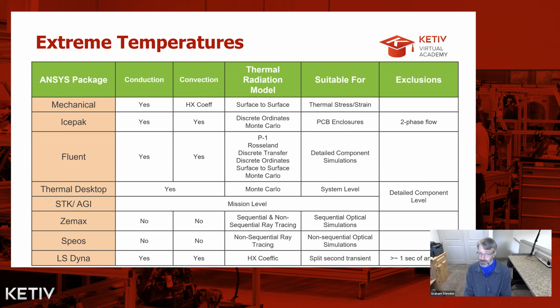And of course, when we're talking about temperature extremes, one of the key factors here is making sure that we have material properties well described as to how they change over the full temperature range. So if I'm going from -200C to +200C, I might need to see how the electrical conductivity of the copper changes over the entire temperature range, so that I can really get the impact of joule heating nailed down well. And so you have additional material property requirements that you might not see on a standard spec sheet that you might be able to use Granta for.